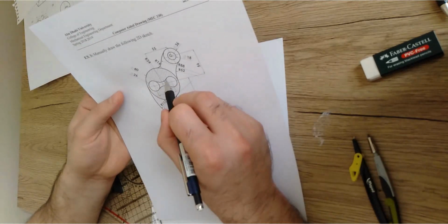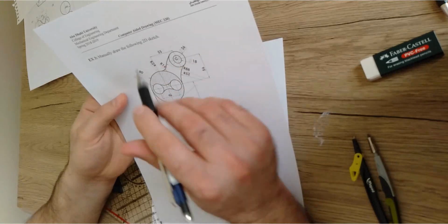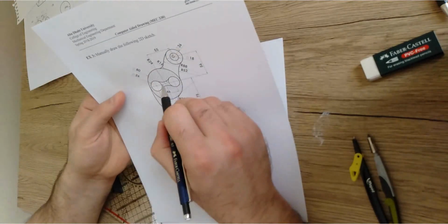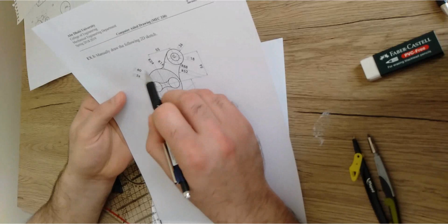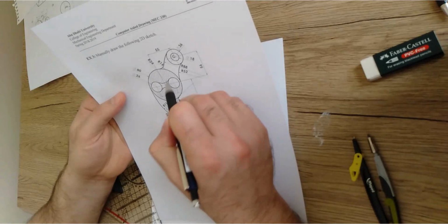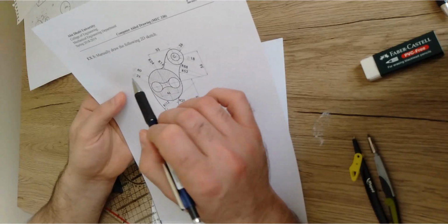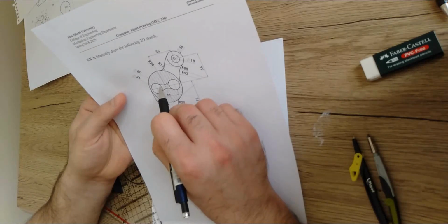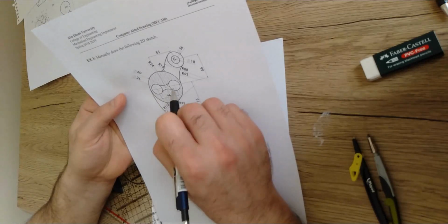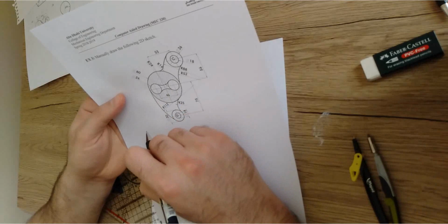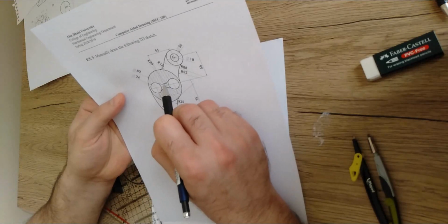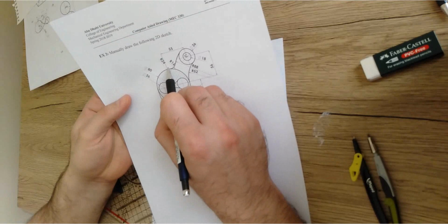Make sense? Where is the center point of this curve? We have no clue. This curve has a radius of 24. This is the only information that we have about this curve. But where is its center? We have no clue. So we have to define this center point using the centers of the two circles that this curve is tangent to. This curve is tangent to this circle and this circle, so I'm going to use these two centers here. But it should be somewhere above here, right?